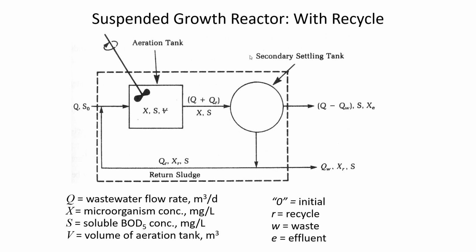So this is a schematic that I think you're going to have to look at and think about. Anybody know what these dashed lines represent? These dashed lines are telling you to do a mass balance. It means consider the flow in and the flow out. There's going to be balance in the volumetric flow rate. So Q in equals Q out. Now, the S, the concentration of substrate out, should be lower than the concentration that went in.